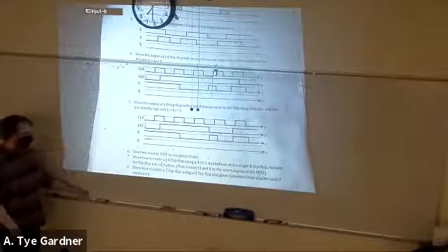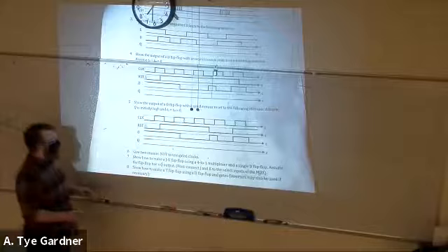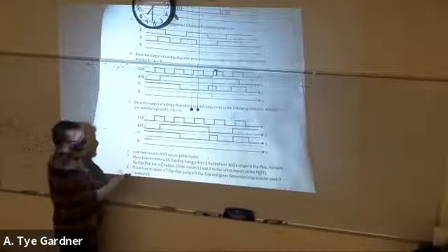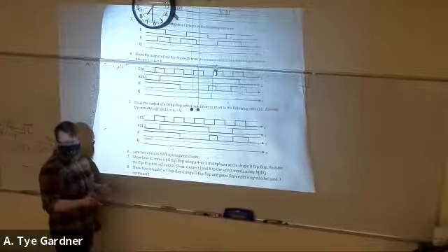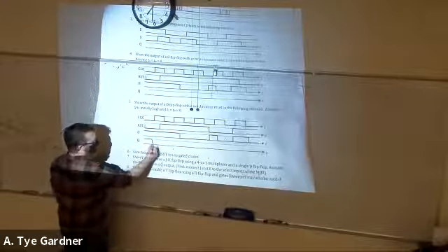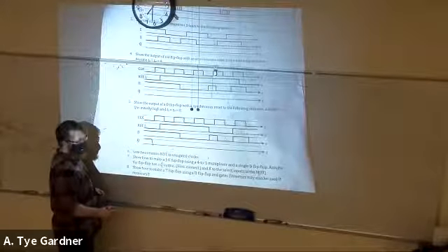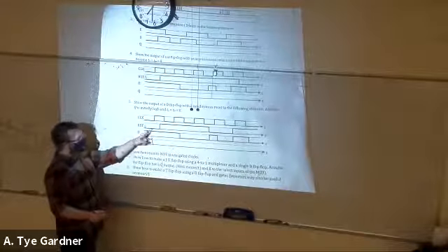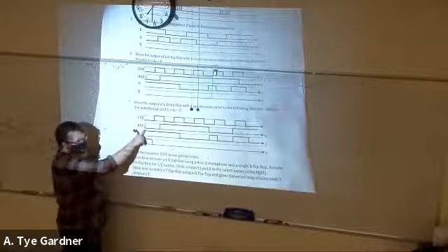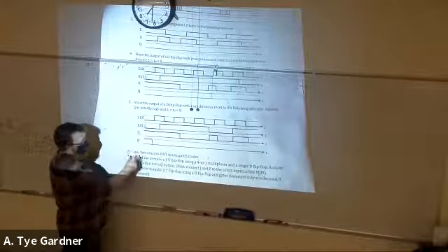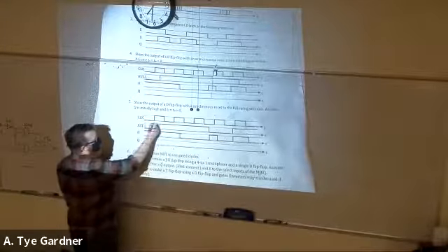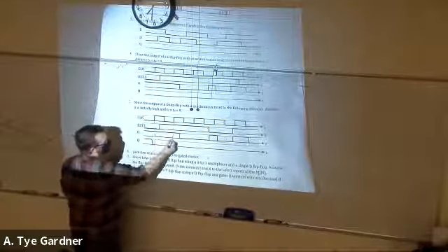Okay, so let's go ahead and look at this. This is kind of a weird one because we talked about how the reset is active low and reset is going to reset to 0. So it's going to drop to 0 as a result of this reset. If you missed that, I don't blame you. I don't particularly like this question because it should start 0, because it shouldn't be able to be 1 with the reset. But fine. The next thing that we want to do is identify locations where it could possibly change.